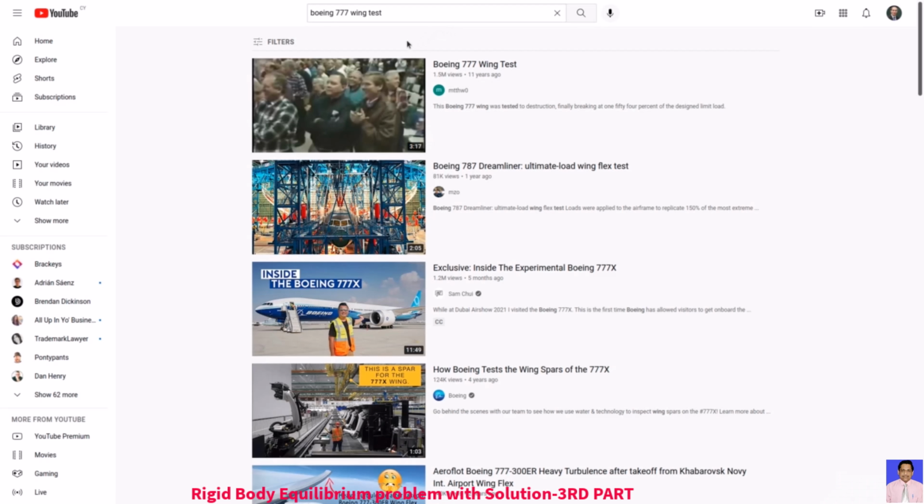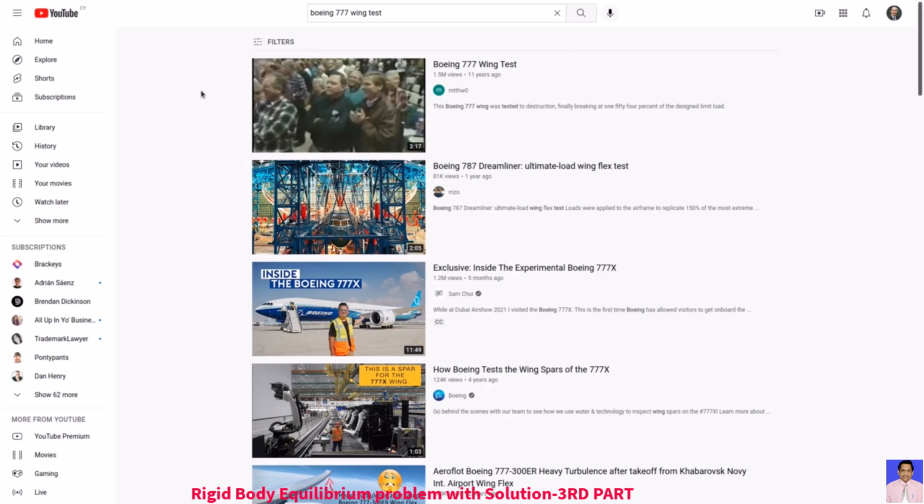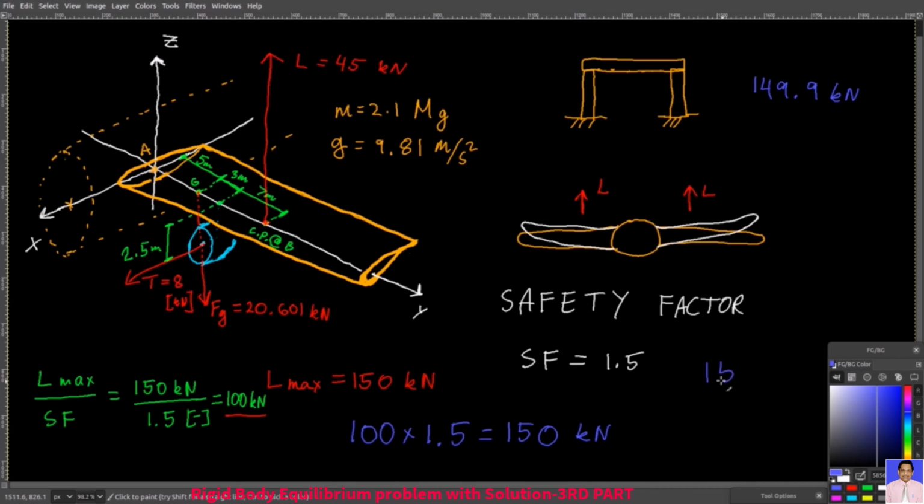If you go on YouTube and you write Boeing 777 wing test, then you can watch this first video here, and in this video they test the wing of Boeing 777, and they say in the video that the goal is to make sure that the wing fails at 150% of the worst case scenario. 150% of the worst case scenario, that's multiplying your worst case scenario by a safety factor of 1.5.